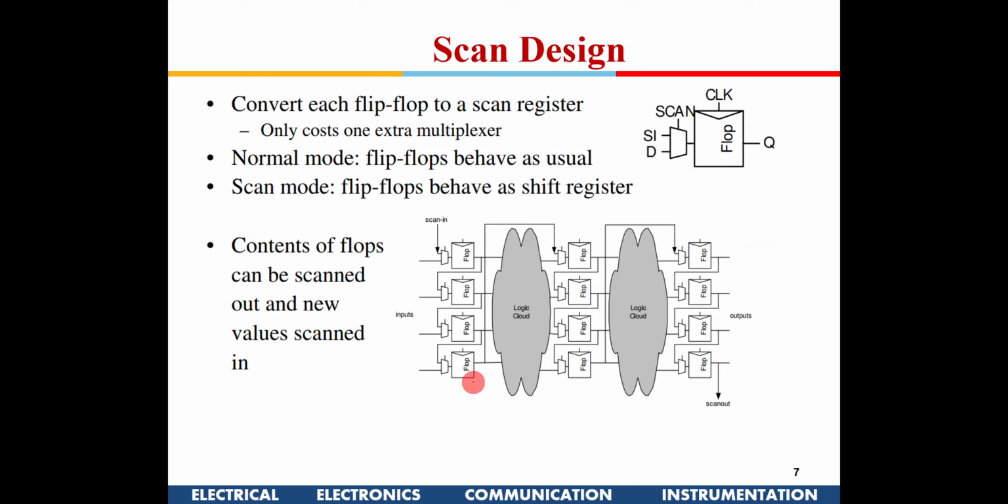But for large VLSI circuits, we have something known as scan design. Normally we learn the advantages of pipelining in our advanced VLSI design, right? Generally these days, in all the processors, you will have a combinational block, then a flip-flop, then a combinational block. This is a flip-flop. This is a pipelined structure. Most processors work on a pipelined architecture, where you don't have a big chain of combinational logic, but small bits.